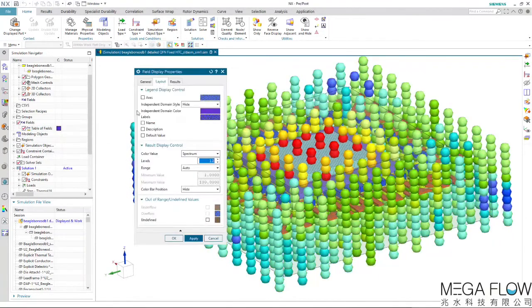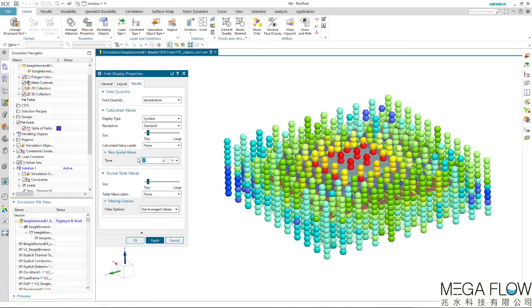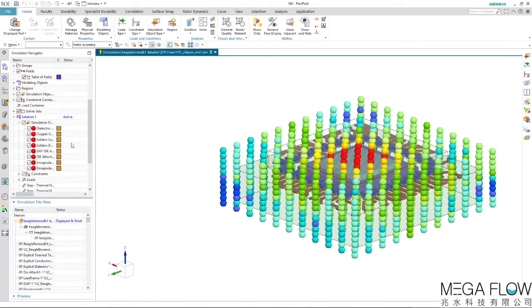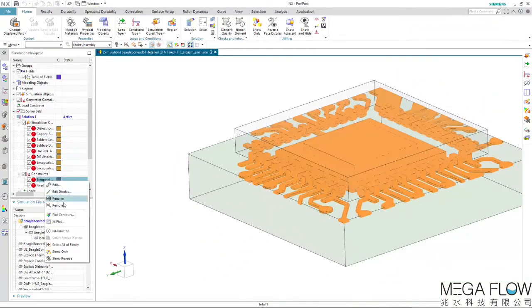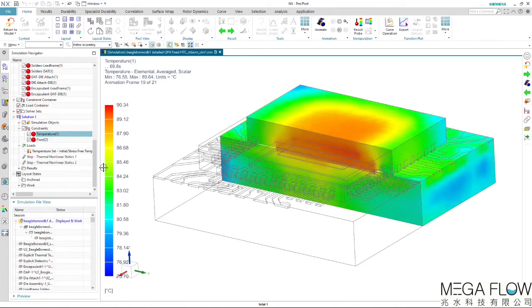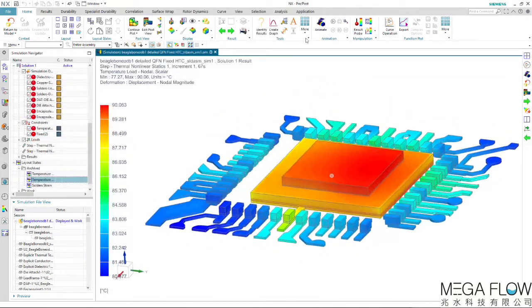3D temperature fields as predicted by Simcenter Flotherm XT are seamlessly mapped onto the equivalent finite element mesh necessary for thermo-mechanical simulation. Once those temperatures are set as load boundary conditions, then a thermo-mechanical simulation can identify areas of undue strain and therefore identify areas that may benefit from remedial design actions so as to minimize that strain and therefore minimize risk of reliability-based failure.